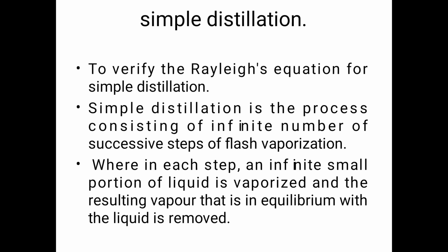So, what is simple distillation? It is to verify Rayleigh's equation for simple distillation. This is a very important equation to find out the number of stages, or the bottom product and top product of the distillation process. Simple distillation is the process consisting of an infinite number of successive steps of flash vaporization, where in each step an infinitely small portion of liquid is vaporized and the resulting vapor that is in equilibrium with the liquid is removed.